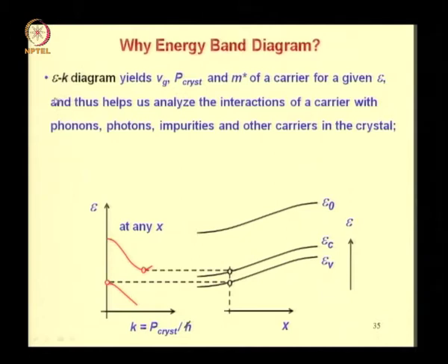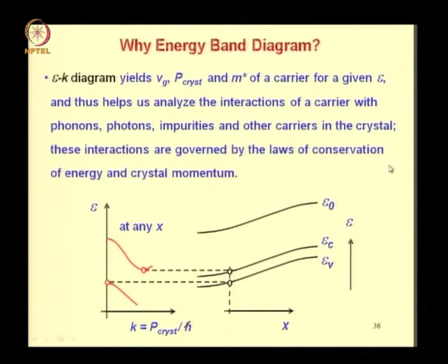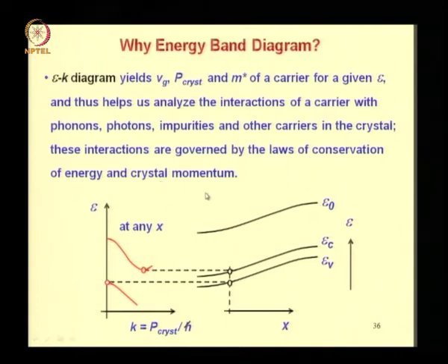And from a knowledge of these quantities, the E-k diagram helps us analyze the interactions of a carrier with the phonons, photons, impurities and other carriers in the crystal. These interactions are governed by the laws of conservation of energy and momentum, namely the crystal momentum.